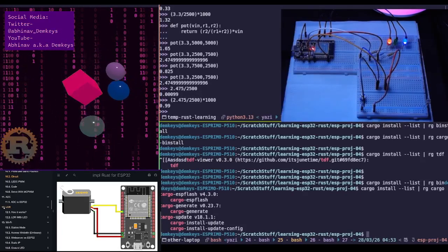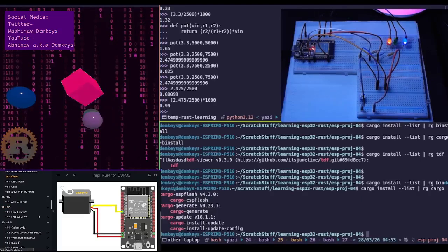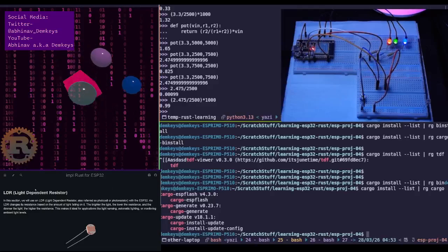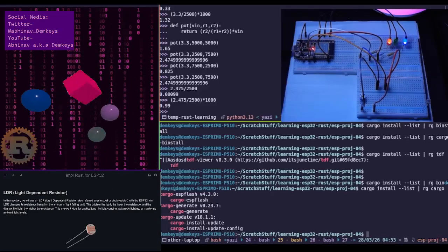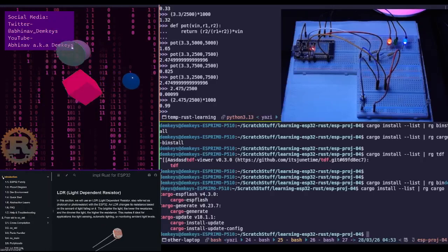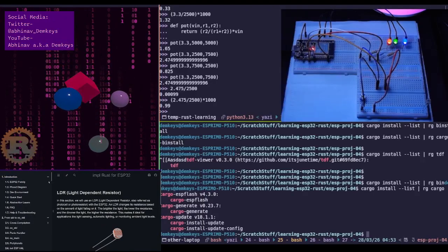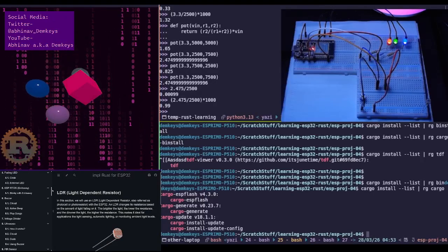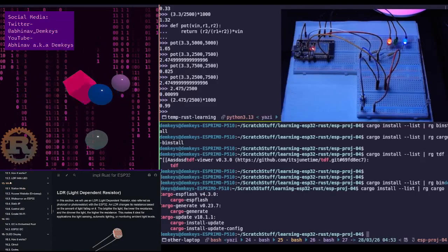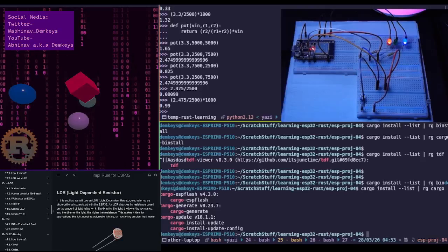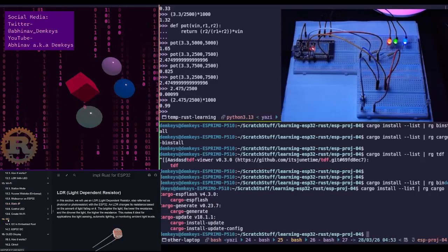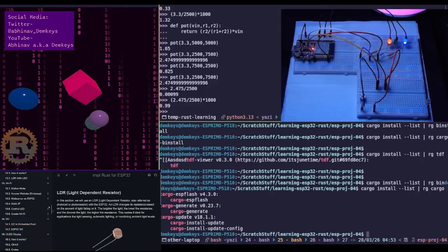Okay, yeah. LDR. So that's going to be the LDR, a light dependent resistor. That's the word. I keep confusing determined and dependent. We can connect it directly into the ESP32 because it's basically a resistor. Then we're going to go into Wi-Fi, which is already on the board, and we can do some interesting stuff with that as well. Then I2C, which is a communication protocol.